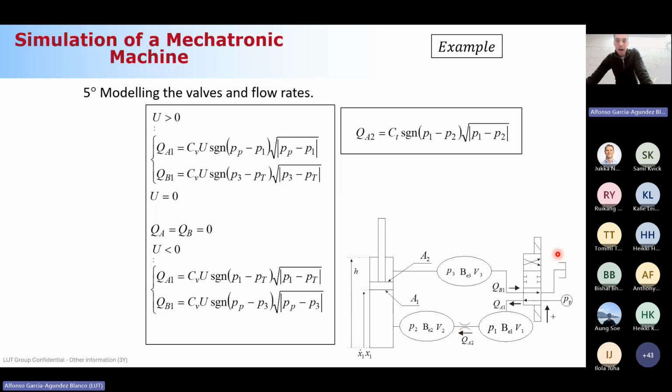motion to the up here or to the right, okay? If you imagine the hydraulic circuit as we usually do it in horizontal position, the positive motion of the directional control valve goes there, okay? Following this arrow. So for u greater than 0, u greater than 0, basically what is representing this is the directional control valve in this configuration, okay? For u greater than 0, we are connecting the pump with control volume 1, okay? So you agree with me that the QA1 should relate the pressure in the pump with the pressure in the control volume 1, P1, no?